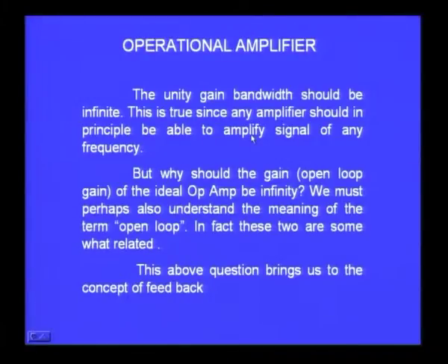We want amplifiers which will amplify all signals irrespective of the frequency, whether it is low frequency or high frequency, by the same magnitude of gain. It is always very difficult to realize such amplifiers; we all know that every amplifier will have a finite bandwidth. So in principle ideally we should have infinite bandwidth, understood, but why should the gain of an ideal operational amplifier be infinity? Or why should a typical operational amplifier have a very large gain, 100,000, why not less?